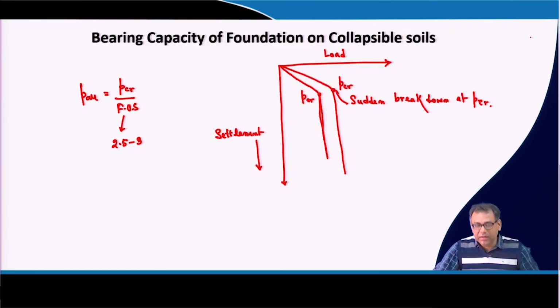We can calculate the load carrying capacity of the foundation by using a plate load test. Once the foundation is to be constructed, if the soil is collapsible, then we can improve that soil by using vibro flotation if the thickness of the soil zone is large. For shallow thickness or shallow depth, we can provide dynamic compaction or the heavy roller, or we can go for ponding also. If these are not possible, then we can extend our foundation beyond the wetting zone by providing pile foundation.